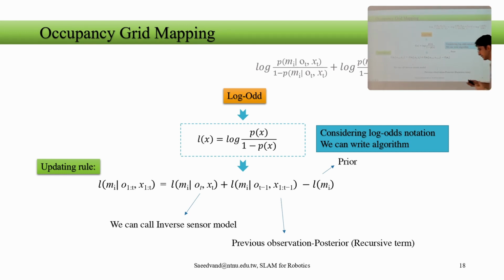After applying the Bayes filter, understanding what we are doing, actually we have a grid cell. Each one of the grid cells should be updated in probability form. If we want to apply the Bayes filter, during the time, as time is increasing, each one comes in with a new probability. So one is posterior, one is prior. The calculation of posterior and prior should finally lead us to achieve the update of probability for that one in the form of the Bayes filter. So this is how we can do that.